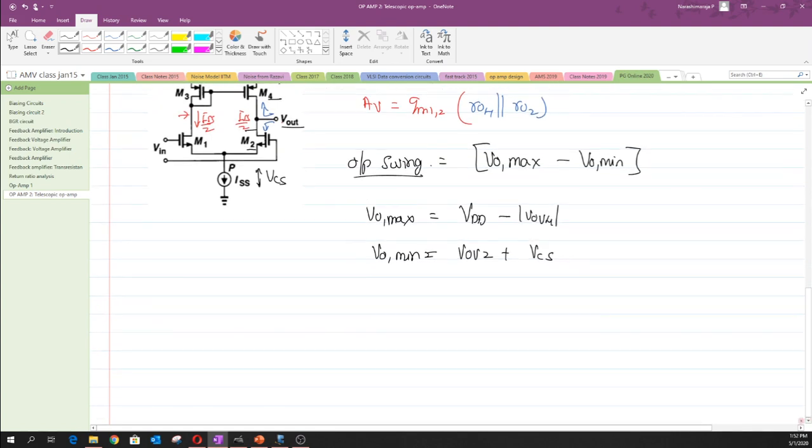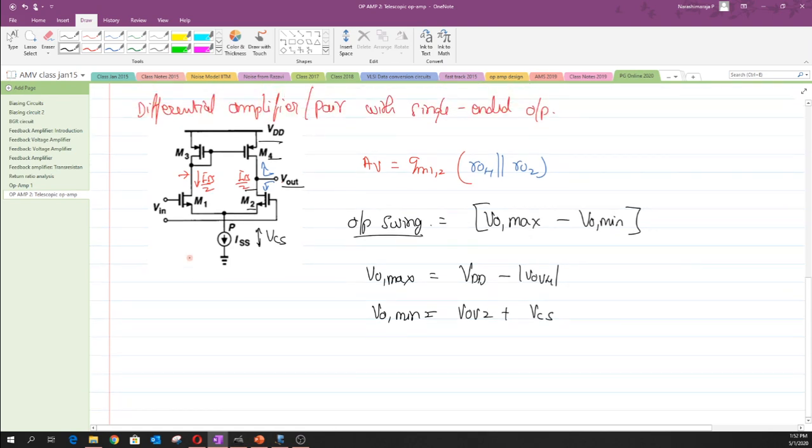There is something else that I need to discuss apart from these simple quantities. In short, when you observe the node X across this mirror transistor M3, this particular node has quite a large amount of capacitance here. Now, why is this capacitance so important? Because we have already discussed the frequency response of any structure, and every node in this particular circuit will contribute some sort of pole inside this gain expression, okay. Now we are more focused on this particular node, where the pole frequency that has been created basically falls